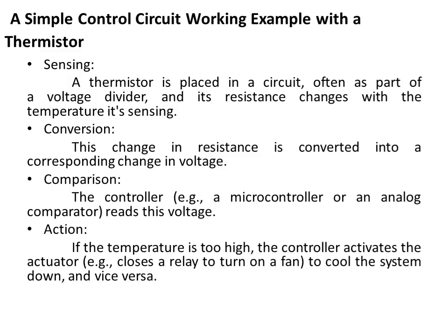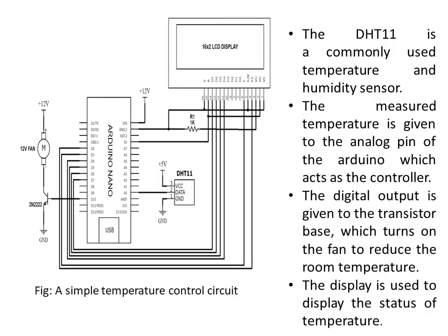Comparison. The controller, that is the microcontroller or an analog comparator, reads this voltage. The action is that if the temperature is too high, the controller activates the actuator, that is closes a relay to turn on a fan to cool the system down, and vice versa. This is a simple temperature